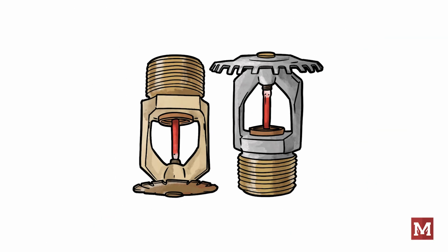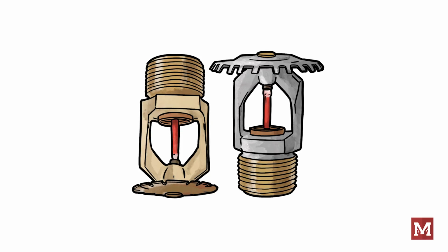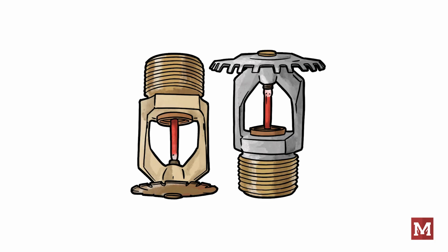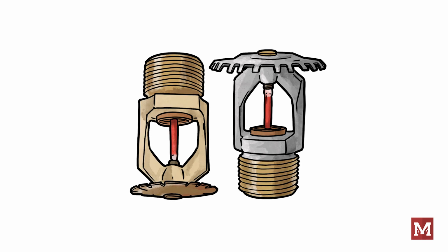Fire sprinklers can be mixed for an area. Uprights can be used for areas with no ceiling, pendants in areas with ceilings, and sidewalls commonly where installing pipe above an area is not an option. These sprinklers can happily be mixed provided some rules are followed. First, if there's upright sprinklers, the K-factor should be the same for the upright sprinklers. The same logic follows for pendant sprinklers and sidewall sprinklers. The K-factor should be the same among the sprinklers with the same orientation.